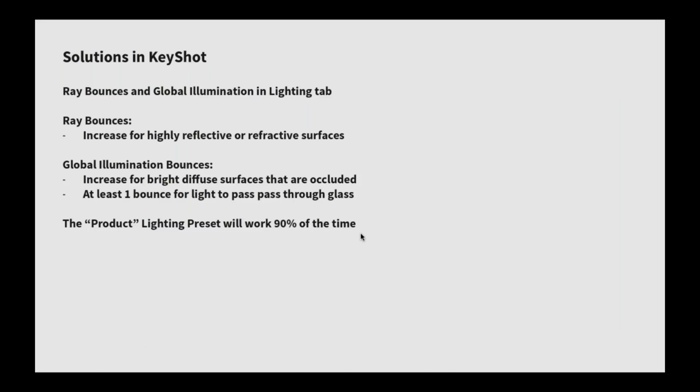The product lighting preset, which you will find in the lighting tab in KeyShot, will actually work in about 90% of the use cases, if not more. So that's definitely a good takeaway message, a good starting point for most any scene.